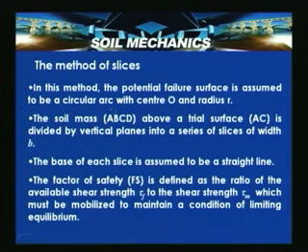The base of each slice is assumed to be a straight line; it is approximated as a straight line. The factor of safety Fs is defined as the ratio of the available shear strength tau f to the shear strength tau m, which must be mobilized to maintain a condition of limiting equilibrium.